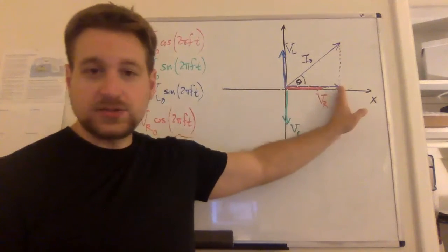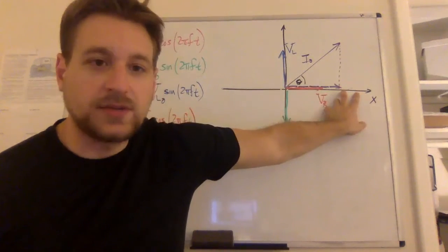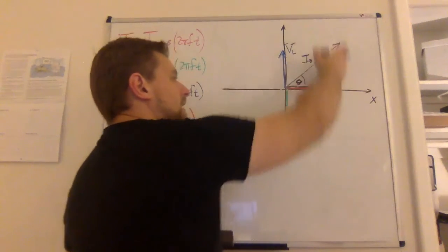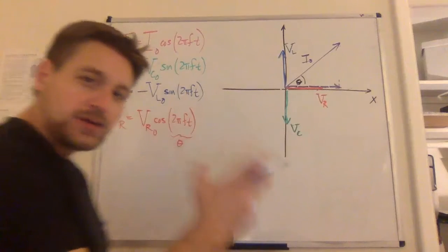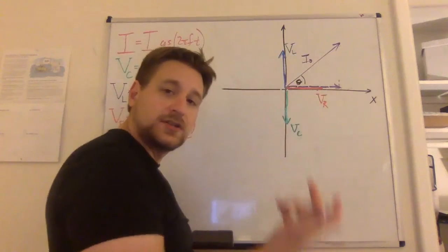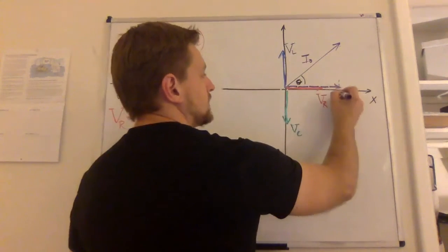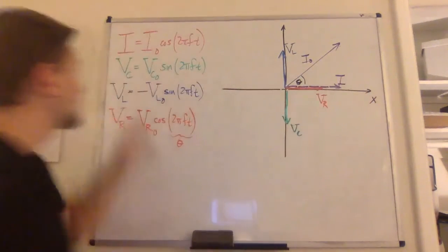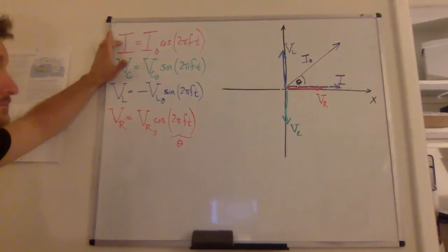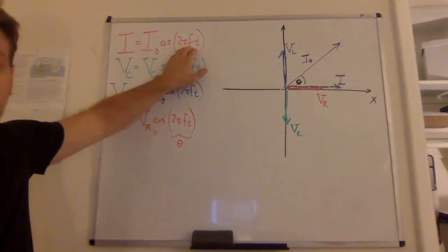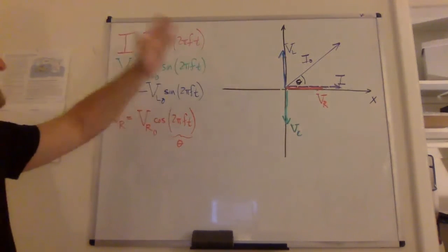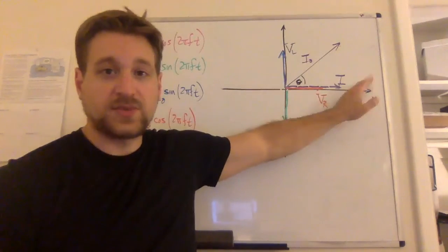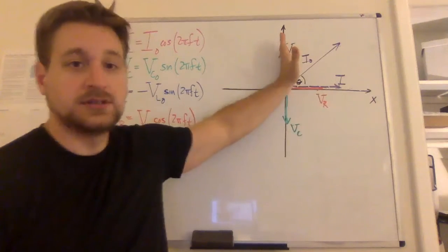Is this slightly shorter thing the original length that came out to here? That x component of the current phasor represents actual I, actual current. As the argument increases, cosine started at 1 and starts to decrease. The x component, as we rotate, starts to decrease from its largest possible value through to 0.